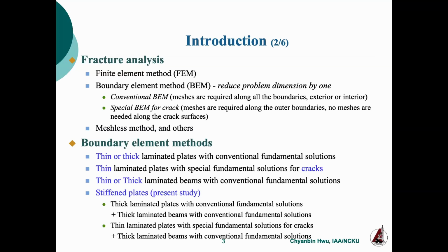I think most of you will be very familiar with the finite element methods, but all of you should know that you need to have a very, very fine mesh near the crack tip. So sometimes we like to have a new method. When we consider a new method, we consider the boundary element method. But we all believe that this stiffened plate is not so unusual. It's very usual, and somebody should have already done this. But when we searched the literature, no one did this. So we try to do this.